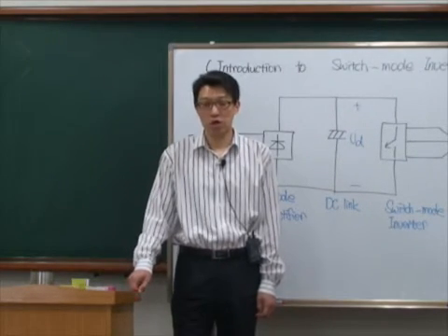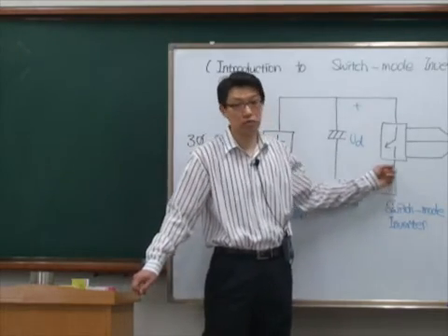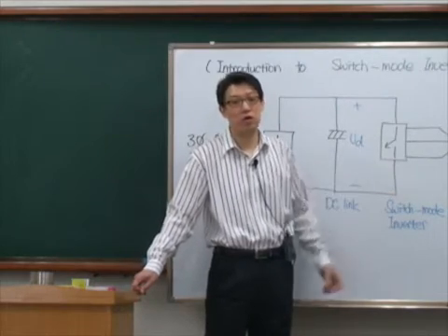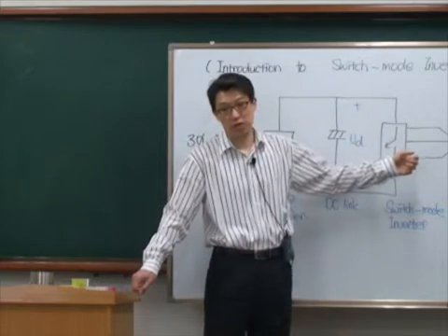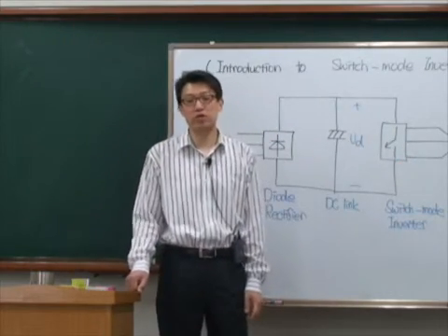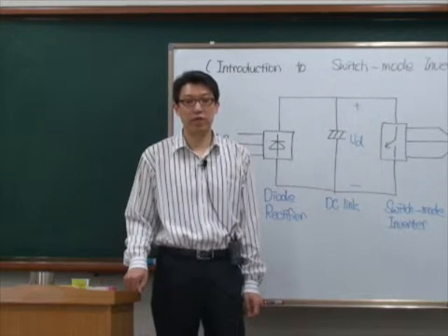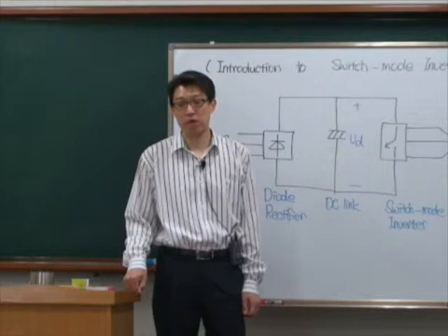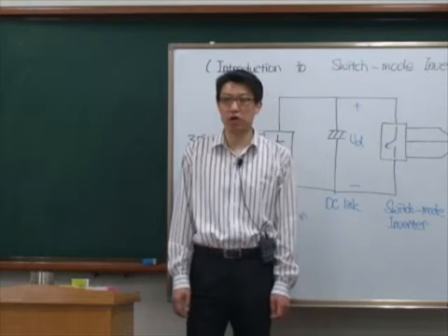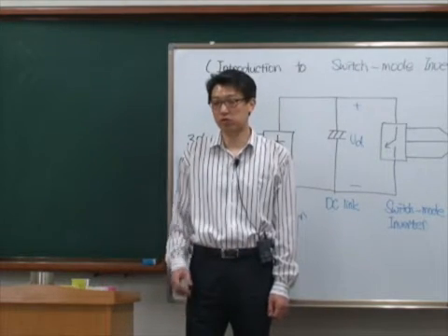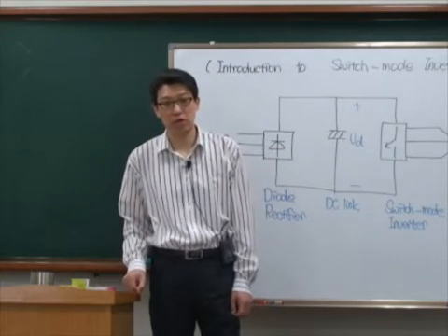So now people start to think about the inverter solution, the switch-mode inverter, right? So this inverter now converts from DC to AC. And then this AC voltage is now very much flexible. Flexible means it can have a variable voltage and variable frequency. So we no longer need any type of mechanical or hydraulic control tools. Like we don't need the valve or any kind of damper.